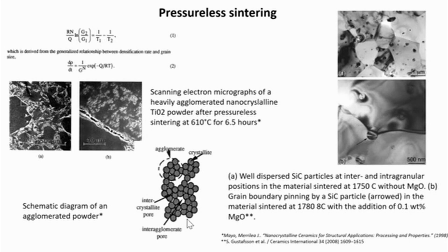For example, Meyer, in her investigation, tested two consolidation methods which helped successfully produce fully dense nanocrystalline ceramic. These include dry pressing at high pressure, around 1 GPa, prior to pressureless sintering, and sinter forging. Both approaches greatly reduce or eliminate the large pores present in a starting compact. Wet processing techniques, though not yet widely used for nanoparticles, also show promise in this regard due to the minimal force required to obtain efficient particle packing.